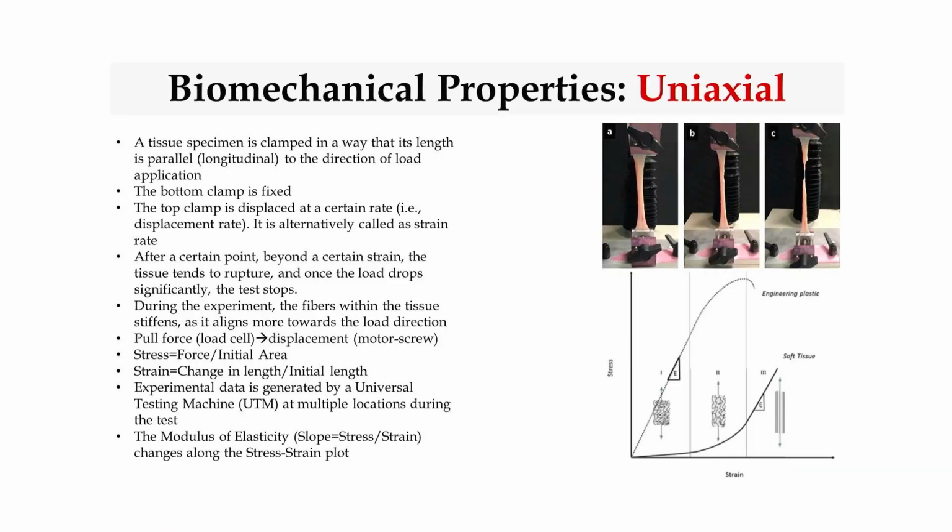Another thing to note, while we are talking about the modulus of elasticity, is that this is not like the hard materials or the metals. The slope keeps on changing. So can you define a single modulus of elasticity for this entire simulated model, the stress versus strain or the model response? You cannot. So there is a range of modulus of elasticity which you want to describe or report. Let's say the modulus of elasticity goes from 20 megapascal to 75 megapascal. This is how you have to define it.